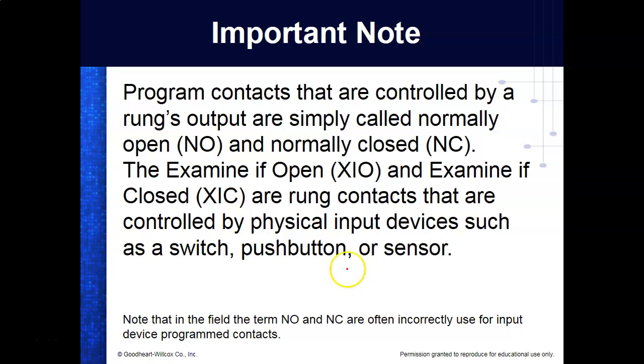So on my inputs, and this has caused a problem, I use that symbol right there. This is examine if open. What that means is it's true if the switch is open.